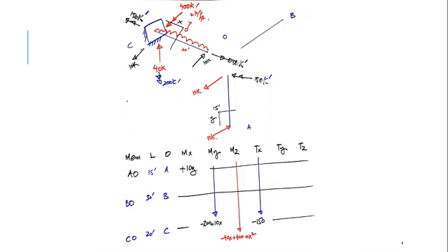Next we have this 10 kip, and this 10 kip is in Z direction, this member is in X, so the moment would be in Y. Moving this towards this point, you will get an anti-clockwise moment. 10 into X, it should be balanced with a clockwise. This is in Z and this member section is in X, so there would be a 10X in Y, so I have mentioned a 10X in MY.